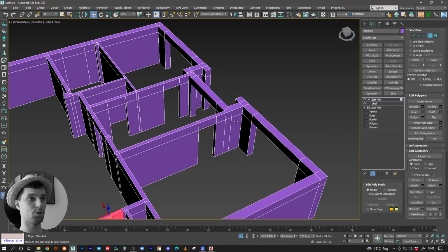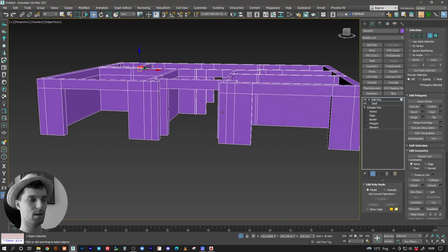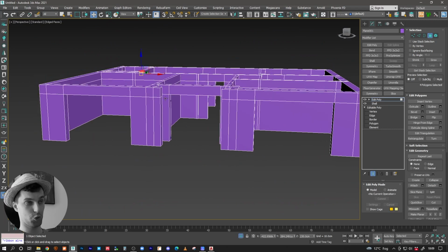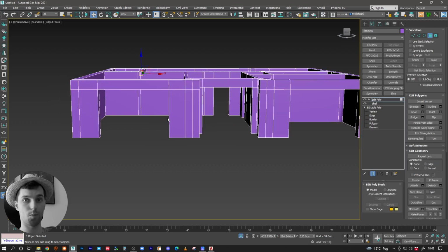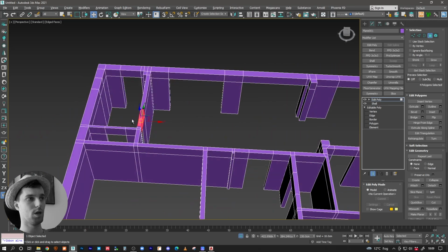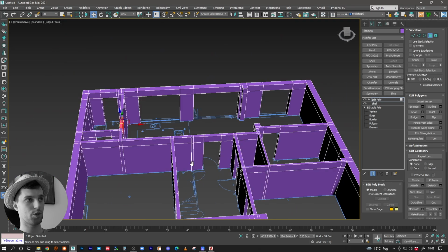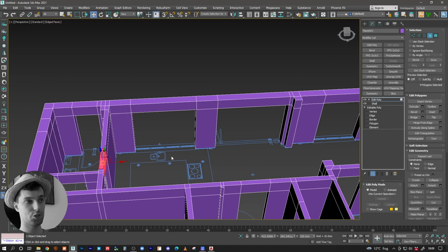The next thing we want to do is, because of this house type, I know 100% sure that all the window sills, or the bottoms of the windows, are not exactly all the same. For example, this is a kitchen window, so the window will be at, I don't know, 110 or 105, because the kitchen countertop or worktop is going to be at 90 centimeters high.